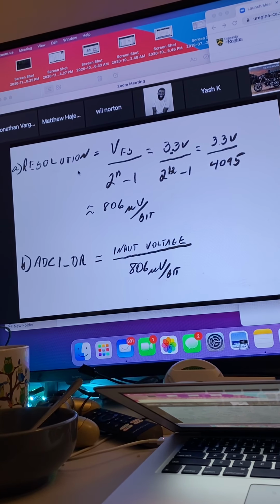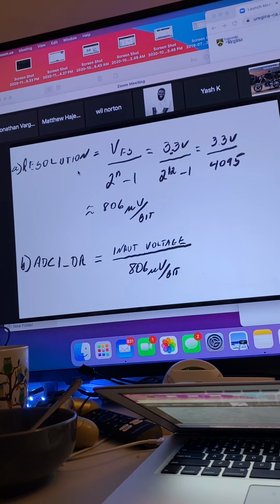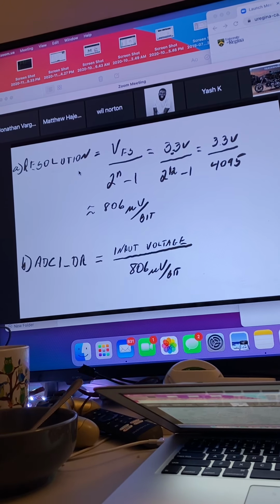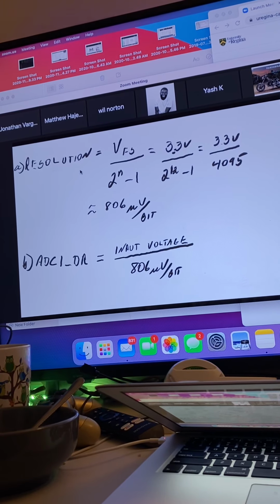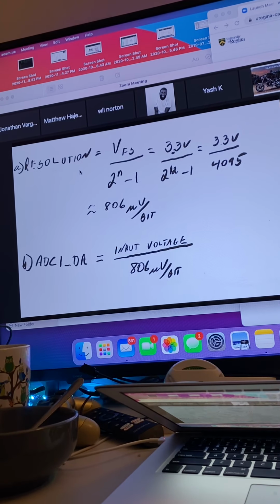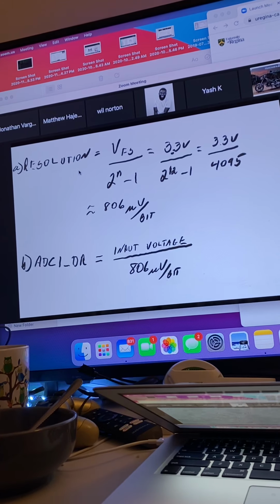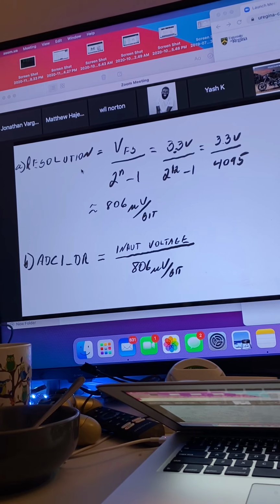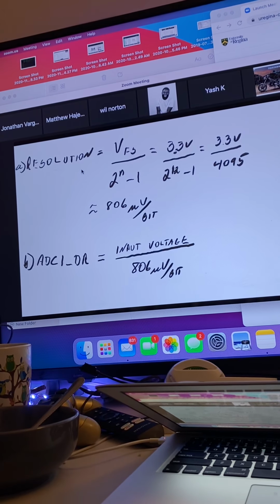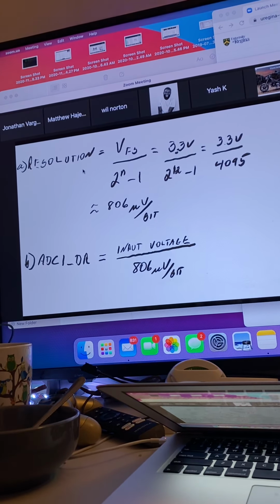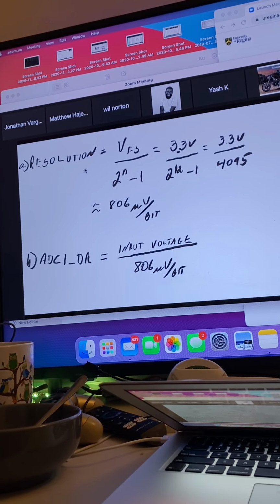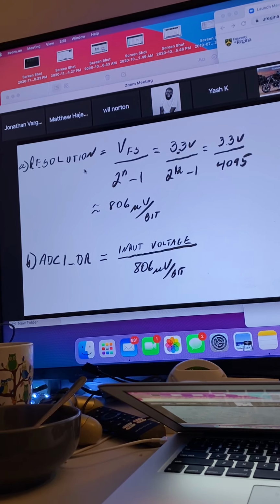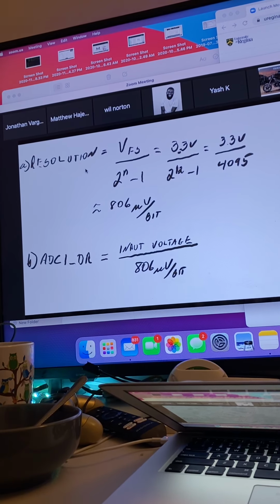For those of you with a VL Discovery board, the likelihood is that your timer will be either timer 1 or timer 4, channels 1 and 2, I think. But if you got a VL, we can always move those numbers around later as we decide different things. Those would be the systems I would look at using. So on a VL Discovery, timer 1, channels 1 and 2, and on a Nucleo, timer 3, channels 1 and 2 for your motor control. One for your left motor, one for your right motor.